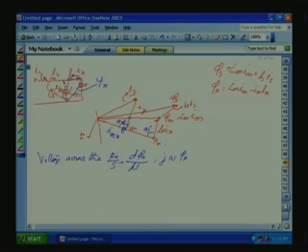So, a current component which is proportional to the flux is already available in IS. If you take the flux psi r and the current component which is responsible for psi r, we are taking that as IMR. IMR is proportional to psi r. Then there is an orthogonal component, perpendicular to IMR, which is the torque producing component. So, IMR plus IR is equal to IS.